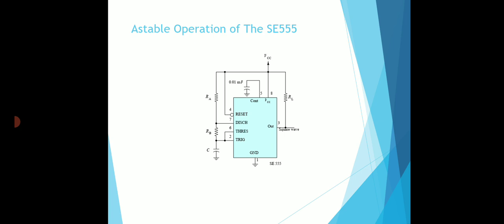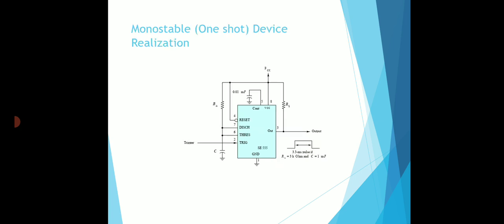And astable operation is something that can be used in several devices. It can operate in both monostable and astable mode. It also requires an external resistor. It is also capable of setting the width of the output pulse in the monostable state. So this provides good frequency stability at 50% duty cycle, which makes it work with other TTL devices and microcontrollers. This IC is mostly used in frequency discriminators, timing circuits, time delay applications, frequency multiplication and division.